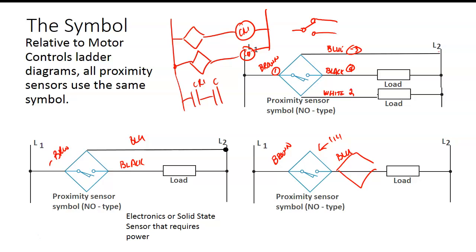I don't think in motor control you did the troubleshooting lab where they put the 2 light bulbs out there, and sometimes it works, sometimes it doesn't, because when you put the light bulbs in series, sometimes the control relay will pick up and sometimes it doesn't. And that's the problem. We get to the point where it's going to be intermittent, and intermittent problems are the hardest to fix. If you're a technician, you like something to break, and you like for it not to work. You don't want it to work intermittently.